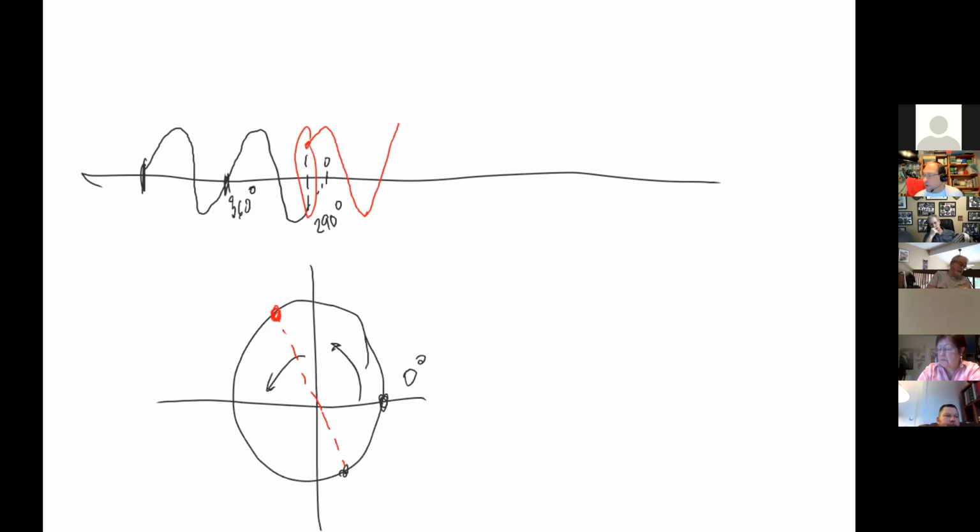We can do binary phase shift keying. This is binary because it's 2 choices. We can also do quadrature. So a quadrant is a 90-degree section. So quadrature phase shift keying is where we can shift by 90 degrees at a time. When would you use these shifts? With quadrature, it can indicate that you have one of 4 different things. In other words, you could encode 2 bits at a time.